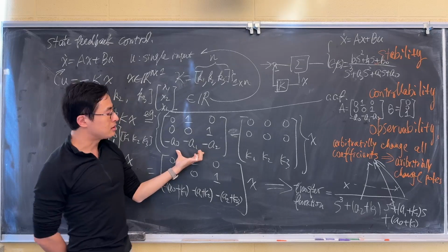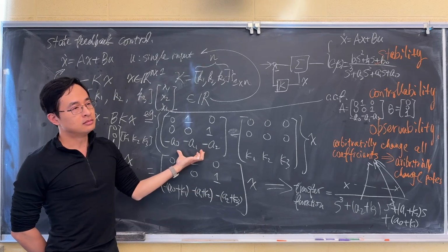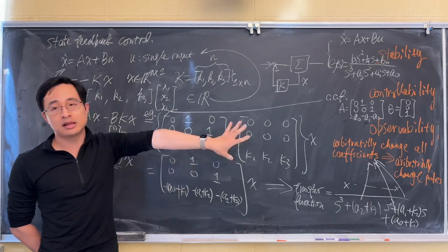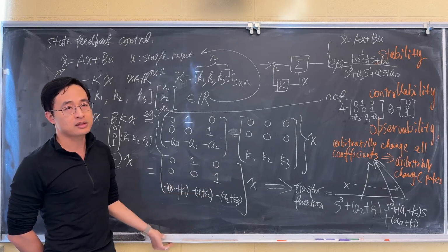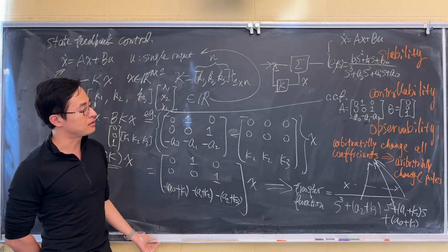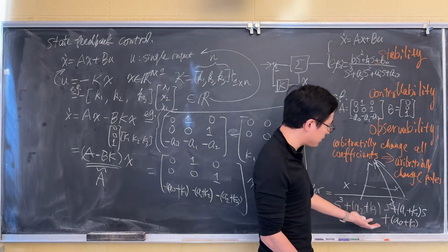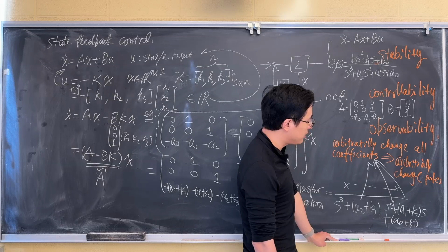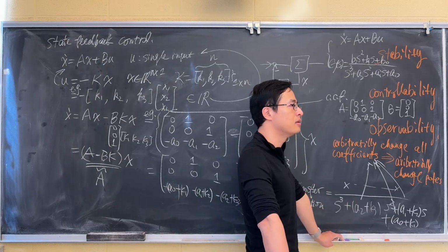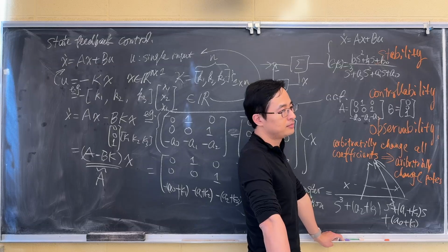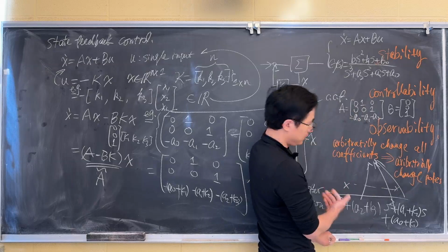So two questions. First, what if it's not in controllable canonical form? Get it there. Exactly. We just learned earlier, if it's controllable but not in controllable canonical form, we can transform the system to be in this canonical form. Second question is, in reality, how do we do this? This is conceptually very powerful. In reality, how should my design be if I have a system that is not stable and I want to make it stable? In reality, we would go in the inverse direction.